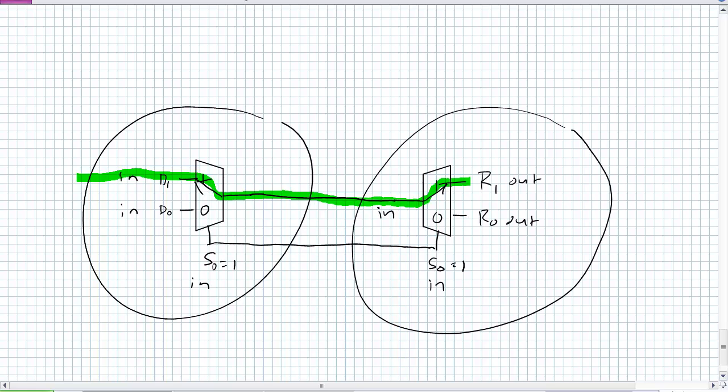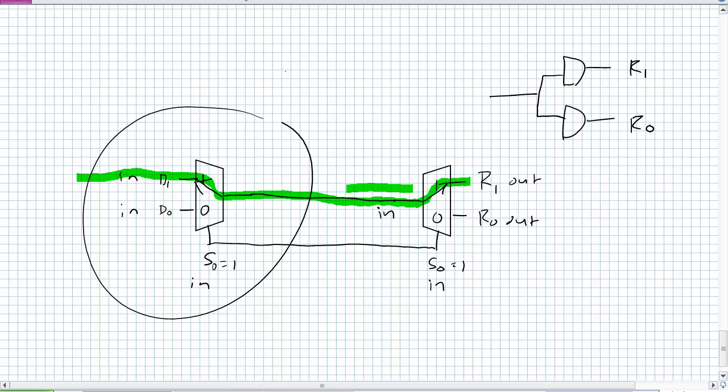If you want to think of it again at the gate level, for an AND gate to be enabled, I'm going to put the serial input on every single AND gate. And then for that particular receiver, I'm just going to put the selects such that that AND gate is enabled. Okay, I'll go ahead and draw exactly what I'm talking about. There are two AND gates. I've got my input, let's just call that X. The output of the multiplexer is the input of the demultiplexer. So there's my input X. It's a digital data signal. It's got data on it. It can be whatever, zeros or ones.